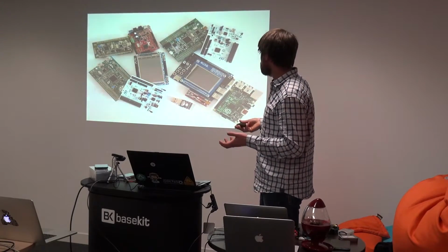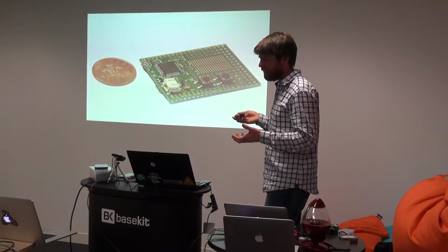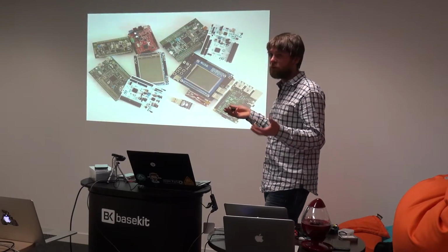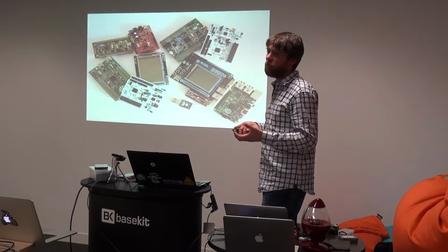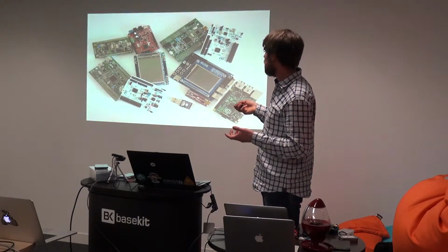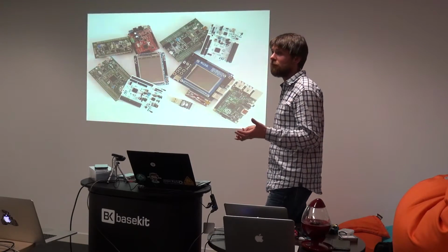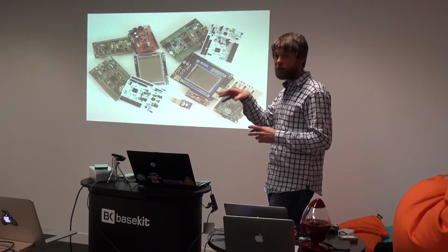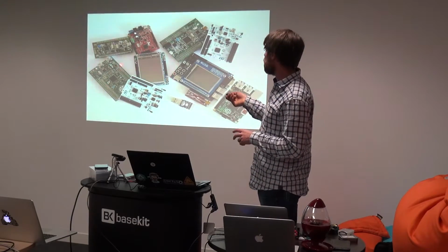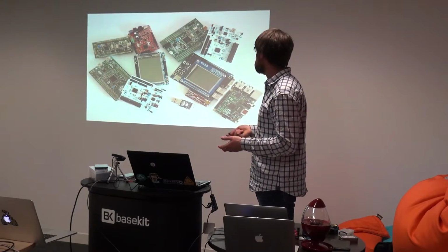A while ago, I did this, which I kickstarted. It's pretty much one of those boards, just simplified a bit, but with all the code pre-installed, so you don't have to worry about trying to flash code onto it. While I've been doing that, these white ones specifically, the mbed-enabled ones, actually appear as a flash drive, and you can write the firmware straight onto them. So it's quite easy. But these other ones would require lots of drivers and lots of software to write the firmware, and it was a real pain.